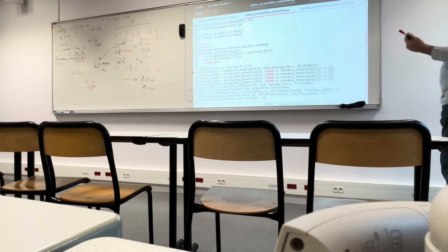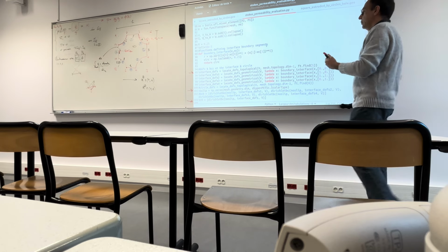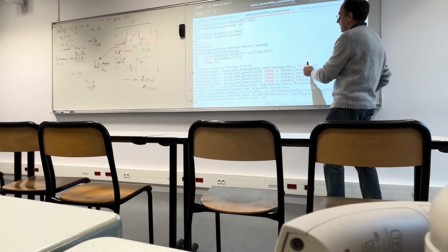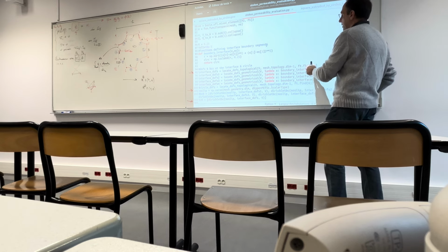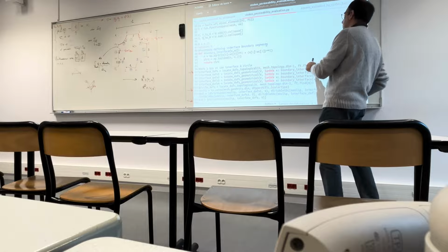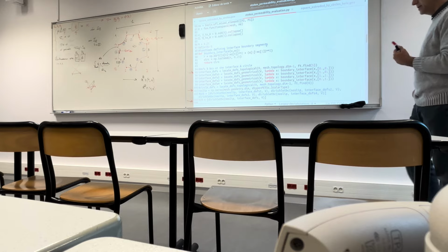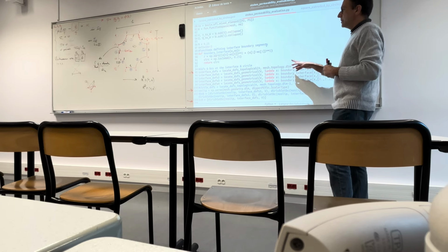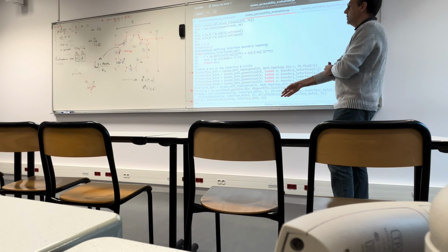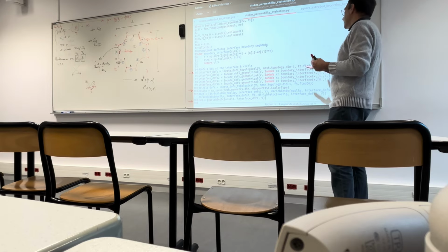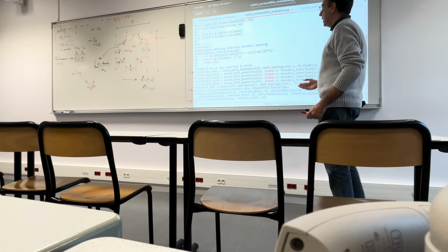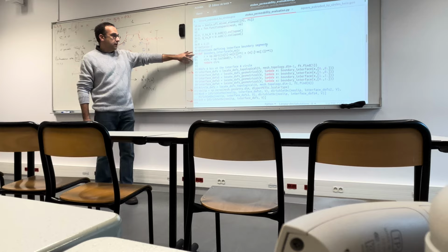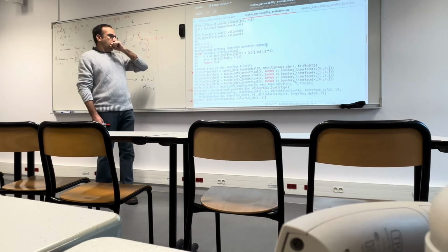So in this case, you do not refer to the label, because here we are using this find function, which looks for the label 5 in this case. Here, on the other hand, we just locate the degrees of freedom geometrically with a restriction. The restriction is introduced via this function.